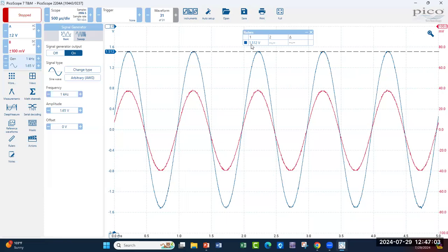The important thing is to see how these waveforms contrast with each other and see if channel B is coming in where it ought to, okay? So let's go ahead and take a look at channel B. Now, channel B is right here in red. It shows B, and it shows that I'm at the 100 millivolt per division scale.